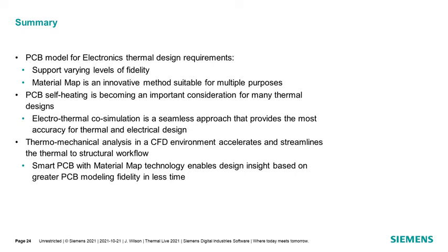And to get the benefit of that prediction, that Joule heating or board heating, in our thermal design process, it's best done either through reading in that power map, which we looked at, or even better, co-simulation, which is going to give you the most accuracy. It's a very seamless process to include the powers directly from a HyperLynx PI simulation, and both sides of the design process, electrical and thermal, benefit from that coupling.